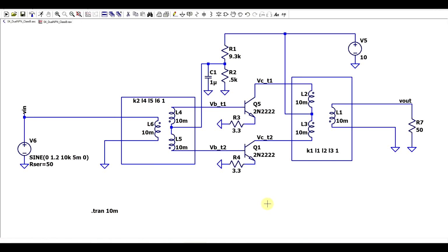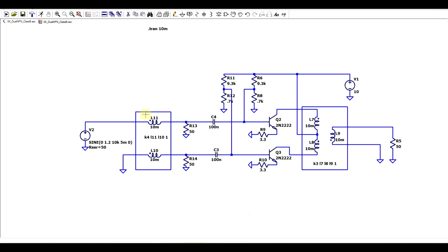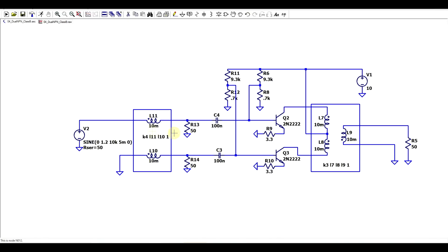Now, one thing that you could do to simplify the design a bit is to start getting rid of this sort of transformer in favor of a bifilar two-winding transformer. So the first design to look at is this one. Here the output looks exactly the same, but on the input we no longer have a complex transformer, but rather one with only two windings. The idea here is that the two transistors have the same impedance anyway, so you can sum the two impedances up, and that is what impedance the input signal will see.